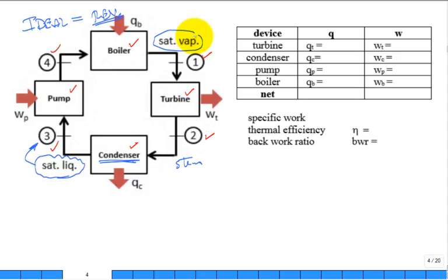It's kind of the minimum superheated steam. It's the saturated vapor that's coming out. If you heated it up some more, it would become superheated steam. That's good. We will analyze power plants where they have superheated steam. But often you peg state 1 to be saturated vapor and state 3 to be saturated liquid.